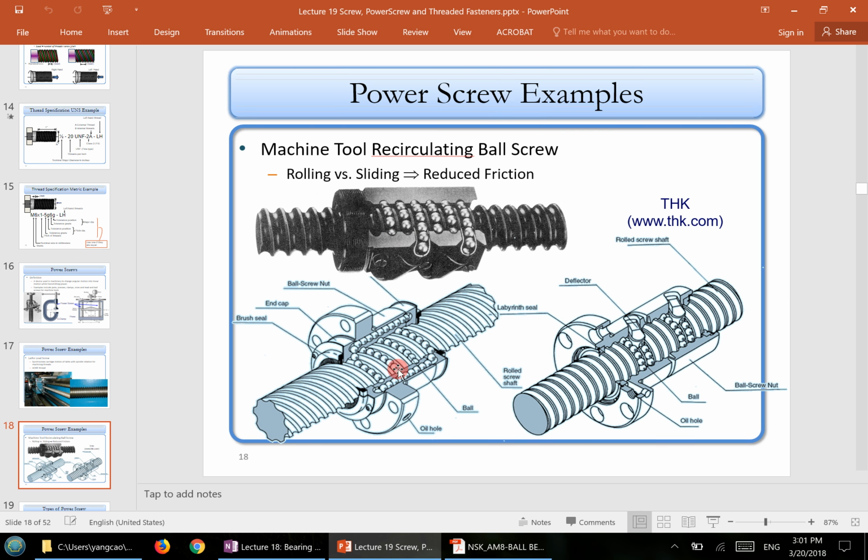But you've got to be careful, right? Don't let the balls fall out. If the balls fall out, you won't be able to put them back. Even if you put them back, it won't be as smooth as it was. It is very typical in many robotics applications with a prismatic arm, where the arm extends and retracts. You have a motor connected to, let's say, the nut right here, so the rotation of the nut causes a linear motion along the axial direction. It's a very useful thing, but it's normally very expensive.